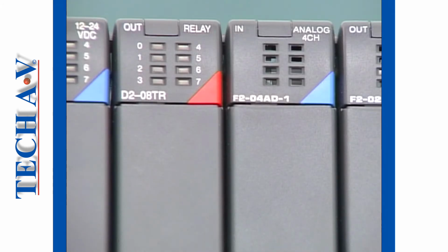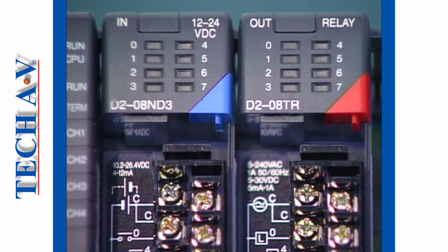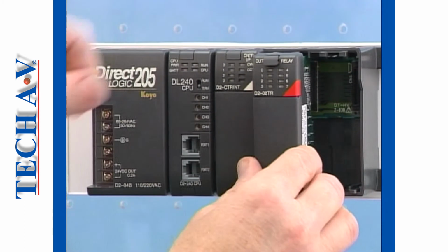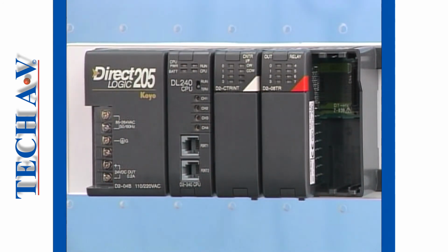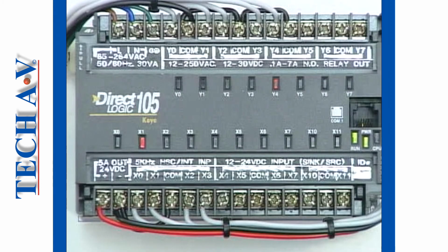These interface circuits are either contained in modules or form an integral part of the PLC itself. The choice of input and output modules or the type of PLC depends on the application, whether the signals are analog or digital, and the number of input and output points required to control the system. One of the big advantages of a modular-based system is that the PLC can be tailored to the application. For smaller control systems, like our block sorting machine with its 4 inputs and 5 outputs, this compact fixed I/O type PLC is more than adequate. It has 10 inputs and 8 outputs, and is suitable for controlling digital input and output devices.